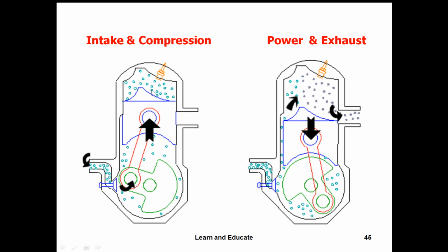So when the piston is moving up, it will get compressed. At the end of this compression stroke, this spark plug will initiate a spark. Ignition will happen. As a result, this charged fuel air mixture will burn, start combustion, and the temperature and pressure will further increase, and the piston will be moving downwards as a result of that heat. So that expansion process will slowly uncover this transfer port, and at the same time the exhaust port.